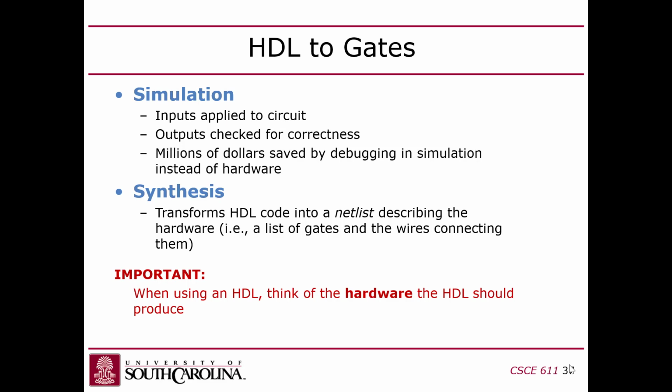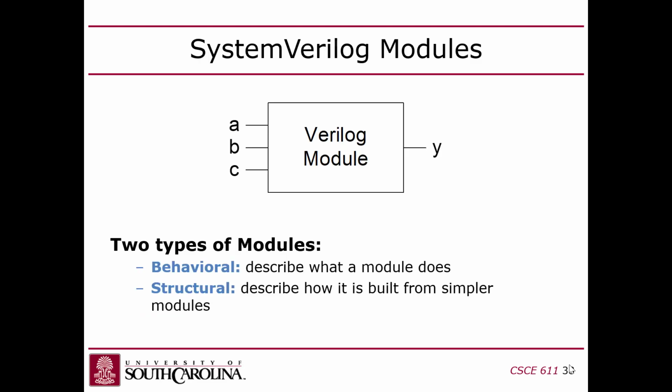Now, that being said, in the first lab you're not going to be doing any simulation. We're going to go straight to synthesis. Part of the reason for that is I want you to experience synthesis to show you why we want to be able to simulate. It's kind of a trial by fire. So you're going to write designs and go straight to the FPGA without any ability to simulate. And if there's a problem with your design, you're going to have to try to fix it on the hardware. But don't worry, it's going to be a simple design, and we're going to give you most of it. But in the second lab, you're going to be doing simulation, just to prepare you for that.